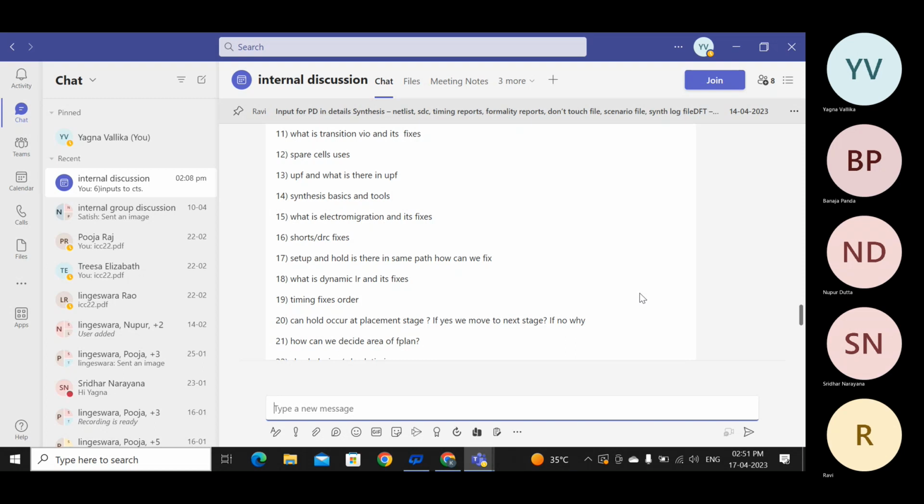So that's why spare cells are inserted. And is there any specific percentage that we insert, 1%, 5% like this? As a physical designer, you should never allow the front end to add more than 0.1 to a maximum of 1%, because adding more spare cells would limit things, since they would all be given specific regions, or you would put them fixed, then it will impact your QoR.